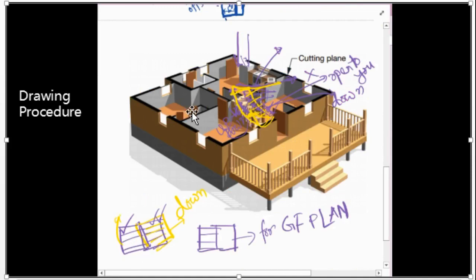One stair, obviously if we cut in this cutting plane, this stair you will see, which will give you a landing over there. But another yellow type of stair you will see, which is coming from the bottom side that is giving you this floor. So the yellow side will be the downstairs, and this portion will be the upstairs, and there will be another upstairs there, but as we have cut it at half of the height, we cannot see the upstairs. This downstairs we will see, and this one we will see.